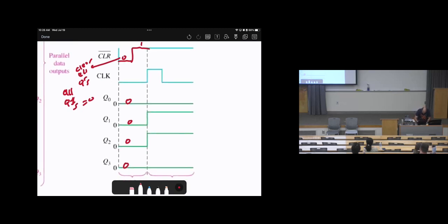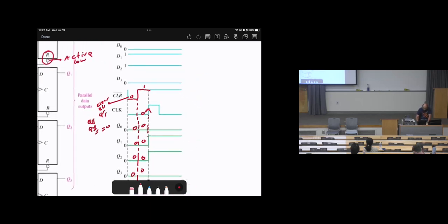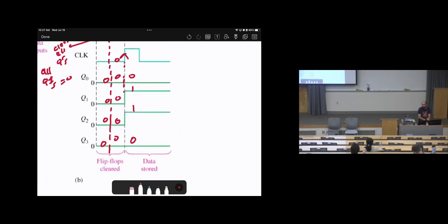So after this point, we will worry about what's happening later. As we know, they are flip-flops, and the update will happen only at the positive edge, or the rising edge. Where's the positive edge? Here is the positive edge, so the updates will happen here. They will remain zeros, holding, until the update occurs. When the update occurs, Q0 will equal D0. D0 is 0, D1 is 1, D2 is 1, D3 is 0. Then I have already updated the values.